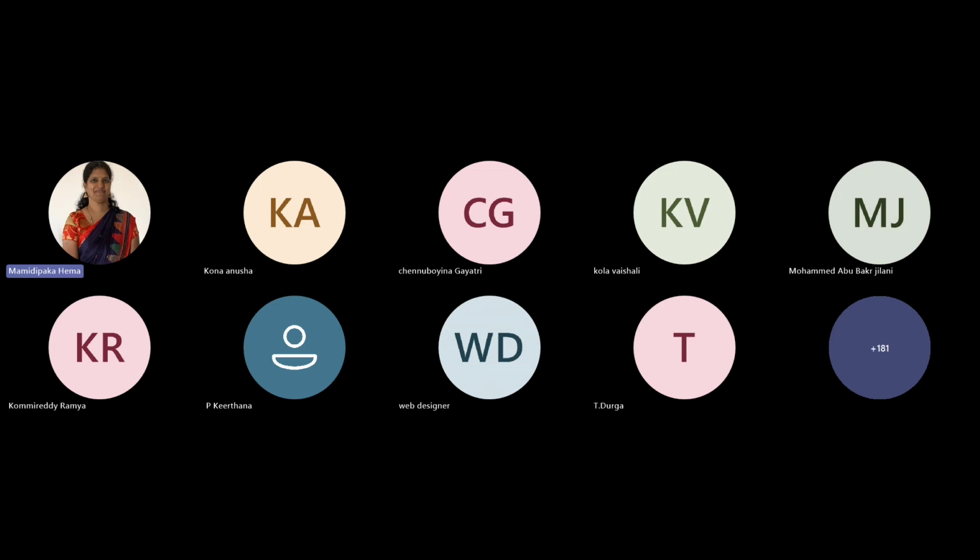Here I have used a DHT11 sensor. It collects the temperature and humidity data. We can also add different types of components to this, and it can be displayed on the LCD board. This is the DHT11 sensor. If any electronic component should work, it needs a power supply, so it has a ground, VCC, as well as the data pin. Initially it sends the power supply, and by using these wires, this process will automatically collect the temperature data.